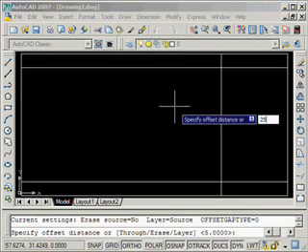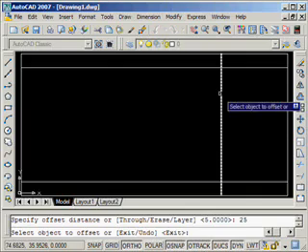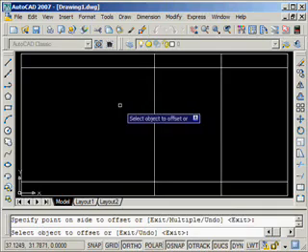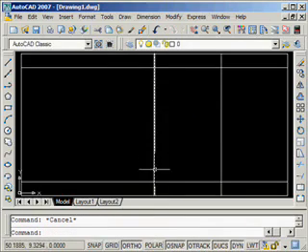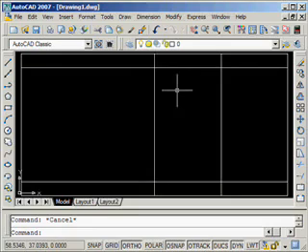My house is 25 feet deep, type in 25, press enter, choose this front line of the house, click it back, and hit escape a couple of times, and now we've got in this inner rectangle the outside dimensions of my house. We want to get rid of these line segments around here, so that brings us to our third command,